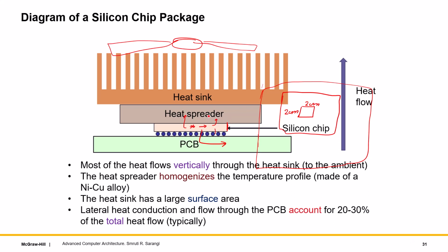Just a small correction: the heat spreader's conductivity, as I said, is 369 watts per meter Kelvin, not watts per Kelvin. I realized that's one mistake that I made. This is also what we have measured in our lab, after disassembling a processor. It could be plus or minus 10% of this. But broadly speaking, the job is to have a very good heat conductor here. It's a nickel copper alloy, and then furthermore pass as much heat as you can to the heat sink on top.